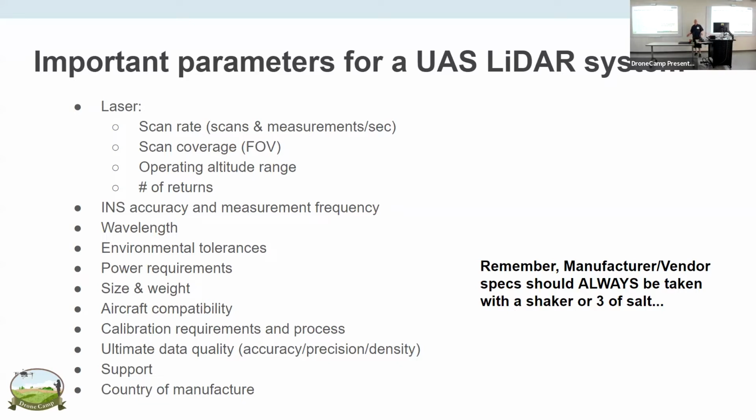How do you calibrate it? A lot of LiDAR have calibration sequences or calibration methods that involve you doing figure eights or lines in certain orientations to each other so that the LiDAR sensor itself and the INS can be married up. The data can be joined up in a way that doesn't give you artifacts. Some systems are really, really simple and fast to calibrate, and some are not so much. So those are also things you want to find out before you spend lots and lots of money on a LiDAR system.